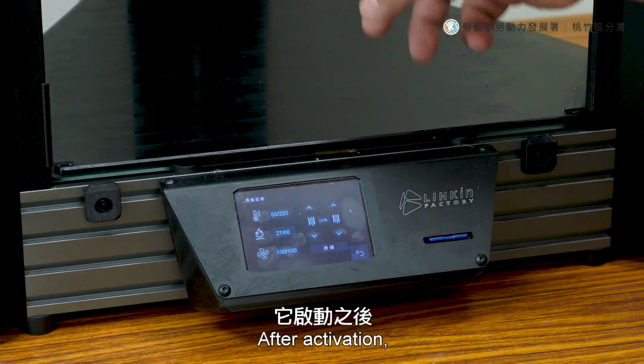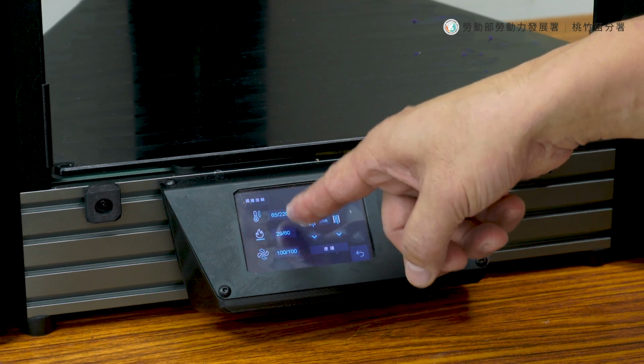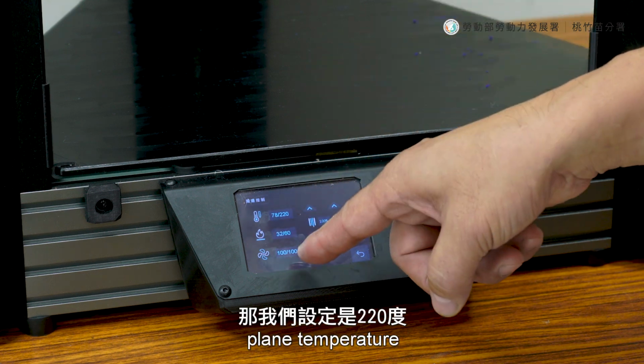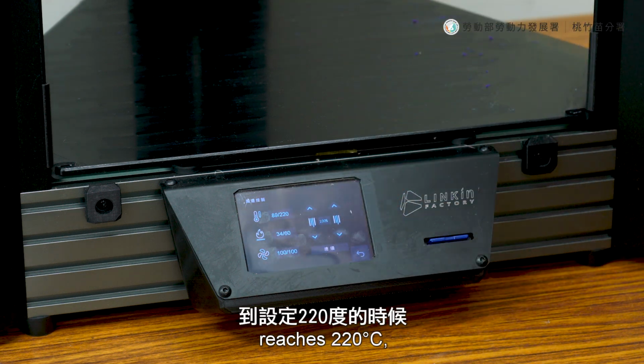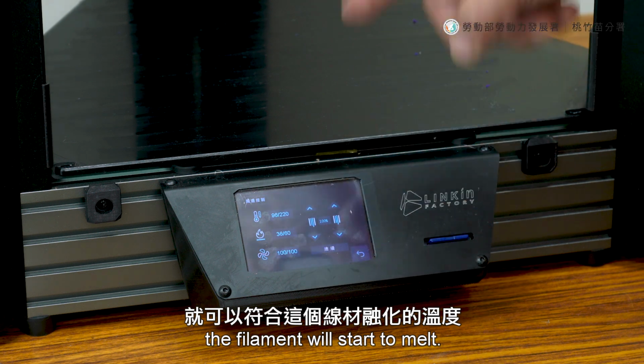After activation, we can hear its operation. That means it is working. The screen shows the temperature rising. The default platform temperature is 65 degrees Celsius. Now it's 33. Once it reaches 220 degrees Celsius, the filament will start to melt.